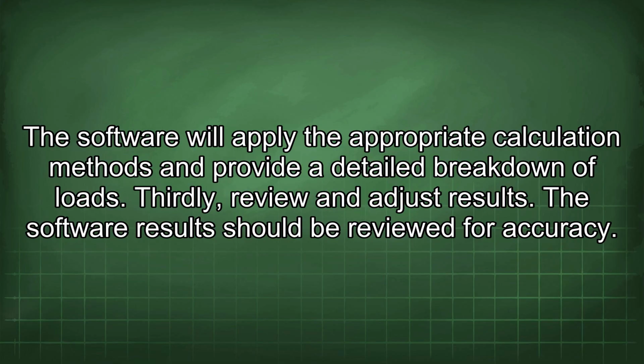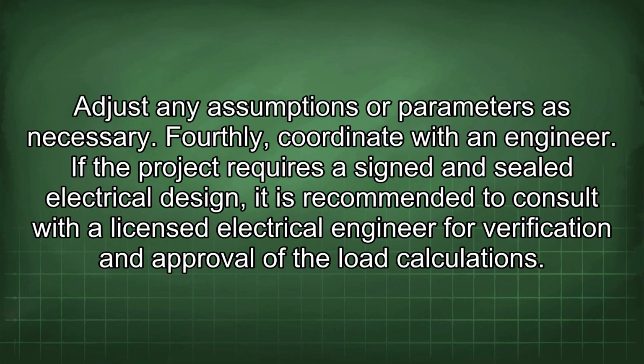Thirdly, review and adjust results. The software results should be reviewed for accuracy. Adjust any assumptions or parameters as necessary. Fourthly, coordinate with an engineer. If the project requires a signed and sealed electrical design, it is recommended to consult with a licensed electrical engineer for verification and approval of the load calculations.